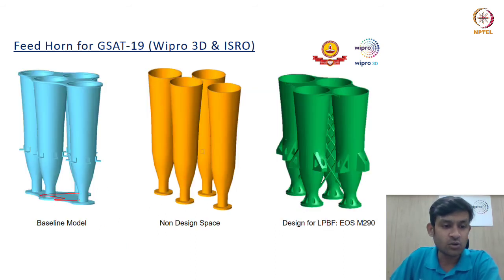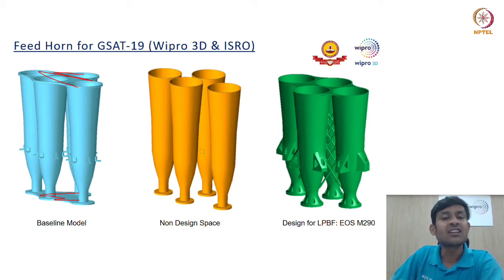They are welded together using these end plates. These end plates are providing rigidity in terms of maintaining the relative position of each and every center of the feed horn. And these end plates are also providing stiffness. But at the time of welding, we need to be really careful about the relative positions of each and every feed horn. That is, this distance to this distance to this distance to this distance shall be maintained.